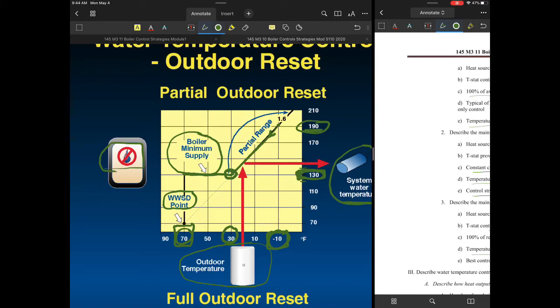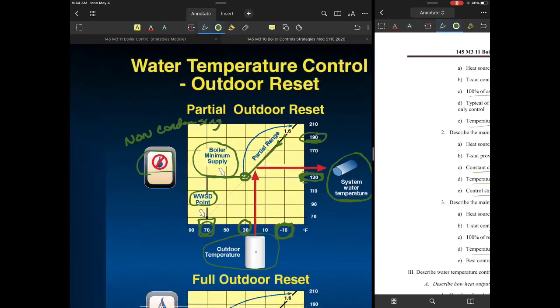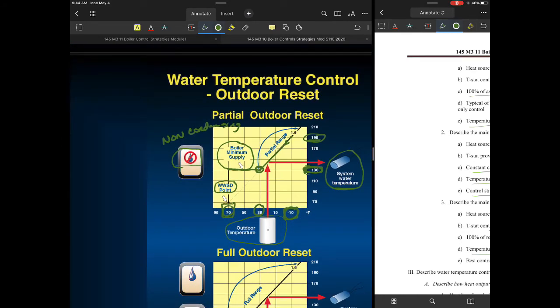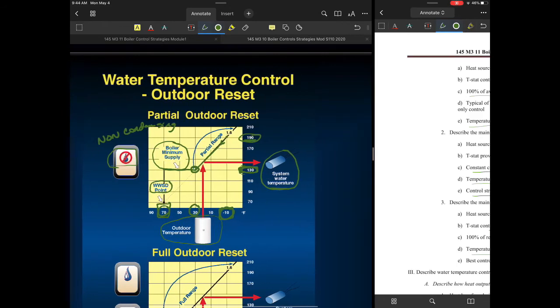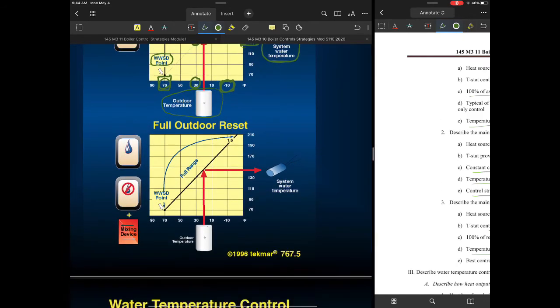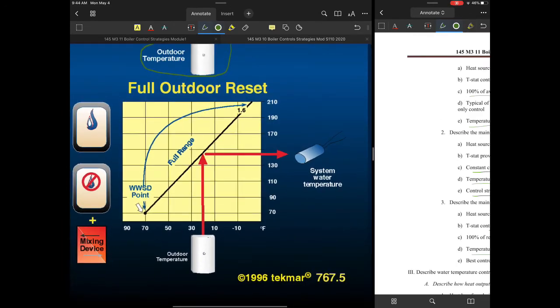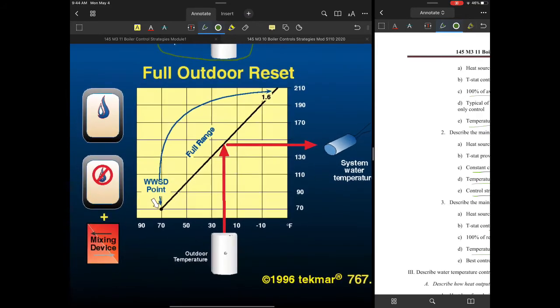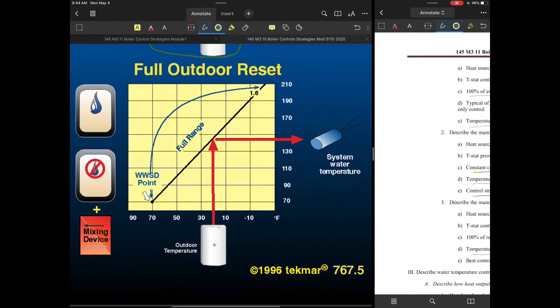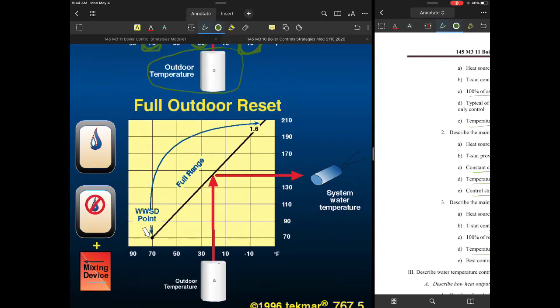This right here is going to be a parameter that you oftentimes will have to put in, depending on the boiler system. And again, what I want to point out here is in this little picture, you notice how they're showing a little water droplet with a slash in there. What they're talking about is non-condensing. So this is going to be true of any non-condensing boiler system, where you would use something like this. So you have to dictate that parameter. Again, it's very typical of most commercial applications.